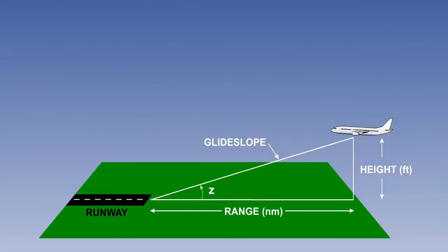If we approximate a nautical mile to 6,000 feet instead of 6,080, this carries out the conversion for us and fits in neatly with the 1 in 60 rule. The conversion is within about 1%, which is close enough for 1 in 60 applications.